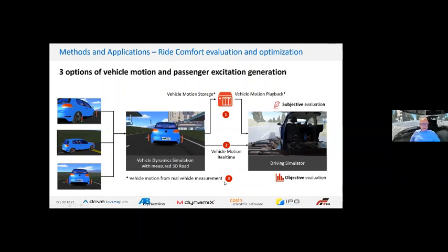Just to show you such a sample, this is a road nearby the Nürburgring. It's called Kempten, an uneven road, which was scanned in 3D. You see a certain behavior of the car. You see also the roll, the pitch, and the primary ride, secondary ride behavior. And as said, not all evaluation can be done in an objective way. So we can do some objectivation, but I would say the little things are somehow important.